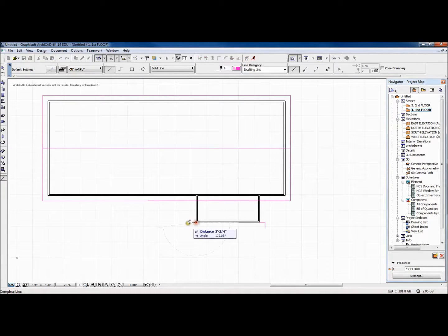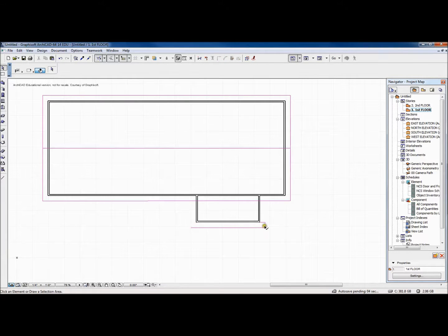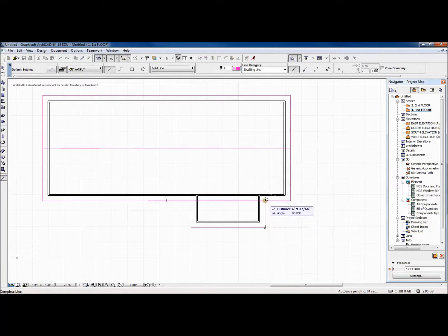And I'll go ahead and put that second mark in, 16 inches. And at this point now I can go ahead and close this, and then I can pick these individual pieces and get rid of them. So what we're going to need to do now is pick up and draw again and close this up. And it's on 90 degrees, so I can close that. And then I will need to make the ridge.